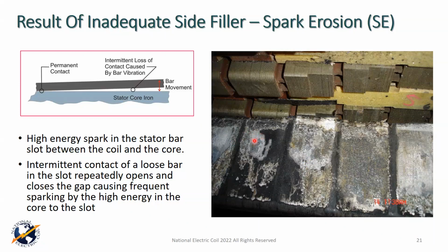And any of you that have ever used 5-minute epoxy, if you mix up 5-minute epoxy and drill a hole and put that epoxy in that hole, and you take a putty knife and go across the top nice and flat, when you come back after it's cured, what you're going to find is you've got a dish in the top of that hole where you put the 5-minute epoxy.